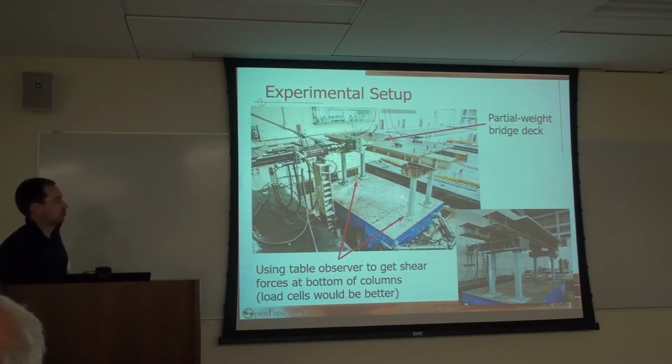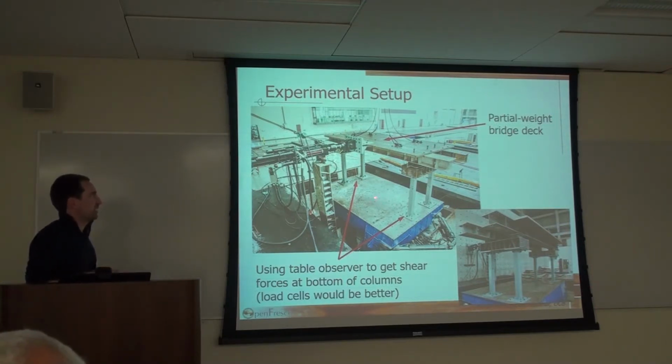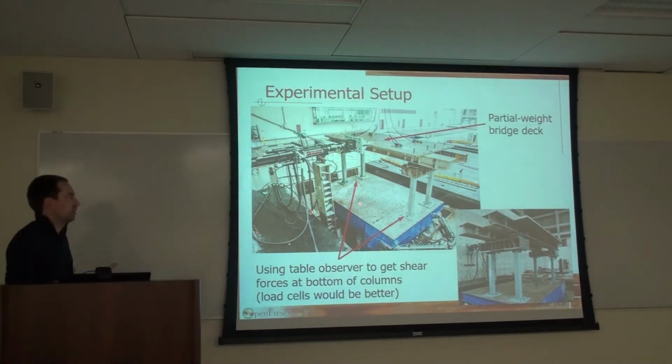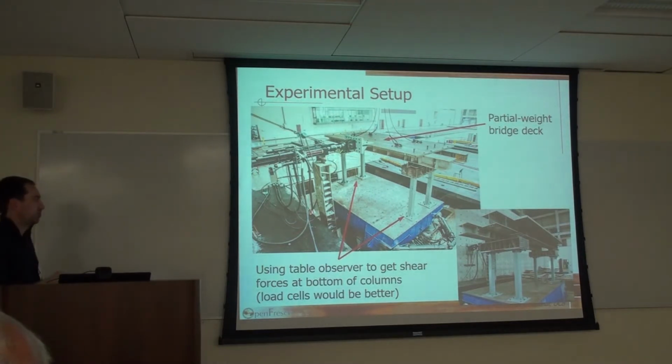So that's the DOF control that Sean Yu was talking about yesterday. So we can directly get the table degrees of freedom. At the table surface, we know what the forces are, and we can get the accelerations. So we get the force at the table degree of freedom, and also use the accelerations, and we estimate as accurately as possible the weight of the table. Then we can take accelerations times the weight of the table, subtract that from our forces at the table degree of freedom, and that should then be the measured force at the base, or at the interface degree of freedom. Okay, so that's the observer that we're doing.